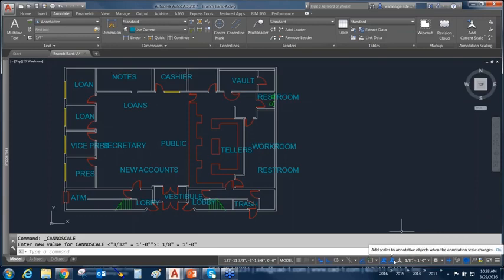Since I've got the icon turned on to automatically add annotation scales, if I don't already have that annotation scale added to all my annotations, then it'll plug it in there for me and it'll show it to me. Now this other icon, as I was mentioning, just says show all of my annotation objects always, regardless of the scale factor. That's one that's really up to you.